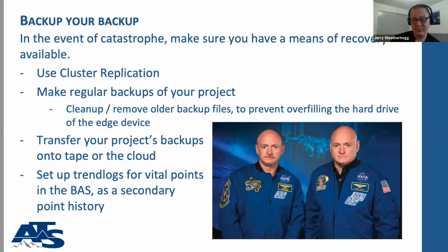Caveat is, if your edge analytics has an issue connecting to a controller, the control system also is likely suffering from that same issue. But it's a good secondary means of backup for the point history data.